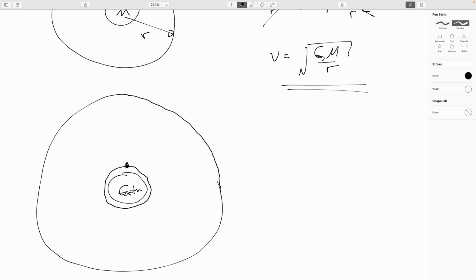You do one burn here, and because you are doing the burn in the same direction that you're going, all the work is going into making kinetic energy and none of it into changing the direction of the spacecraft. So it's as efficient a burn as you can do.